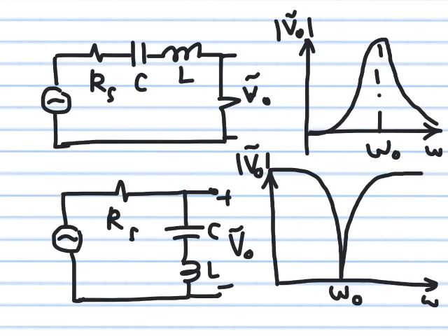Notice when I say the impedance of the inductor is large, I say j1000, I mean it's effectively representing very high resistance to current, but this j talks about the phase shift between the voltage and the current across it. But still, it offers pretty high impedance. It's trying to impede the flow of current. Okay, so effectively, when this is j infinity, this branch here is open circuit.